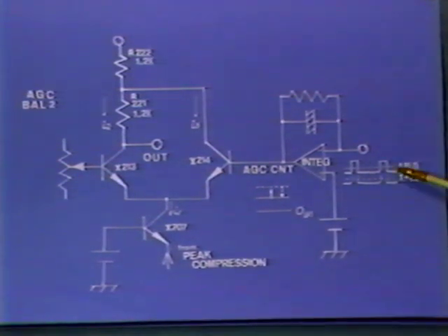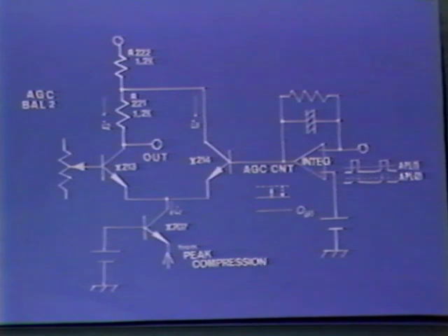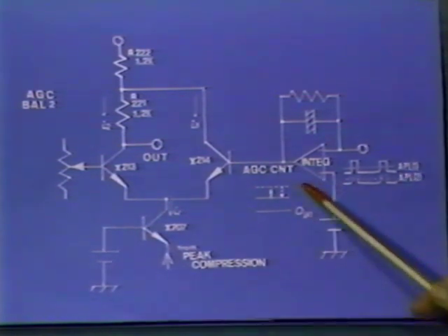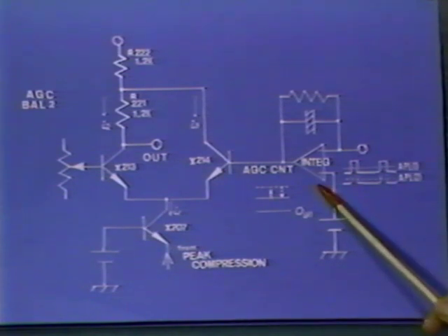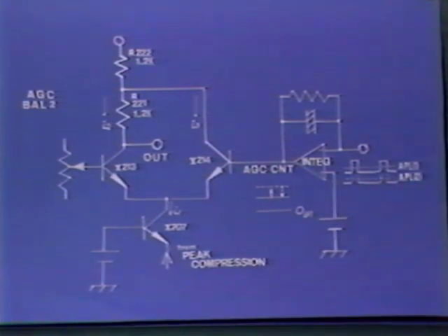For example, think about the case that the object's illuminance becomes small to reduce the image signal in this way. Its mean level becomes higher during the blanking period when it's clamped at the specified level. This signal of the mean level is processed by the operational amplifier with its output being this small.